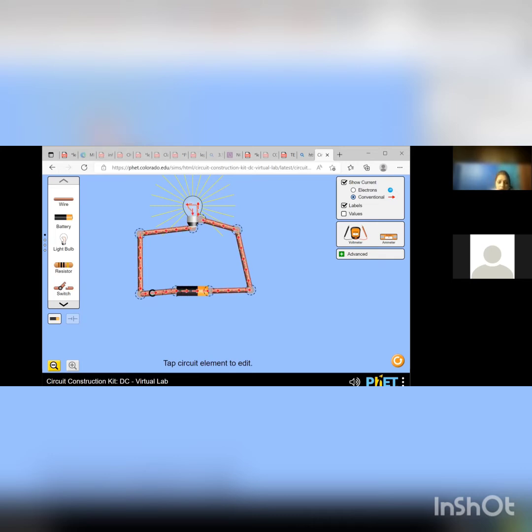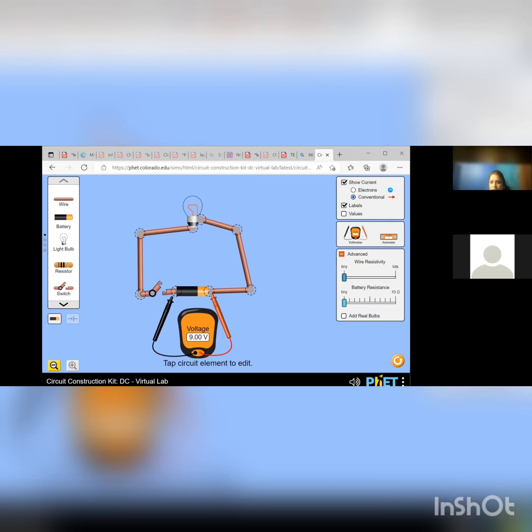Now, again, I open the switch. I take a multimeter. A multimeter measures multiple things, but here it is a voltmeter, a voltage measuring instrument. I'm going to measure the potential difference across this positive and negative. It gives me 9 volts. Now let us see. I say let there be some battery resistance, so I have set some battery resistance. You will understand what it means.